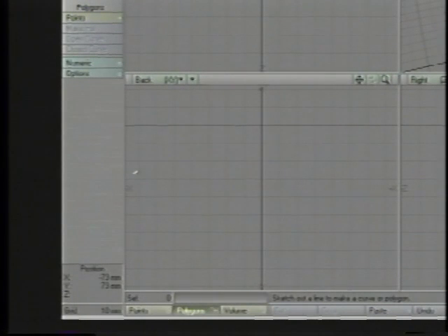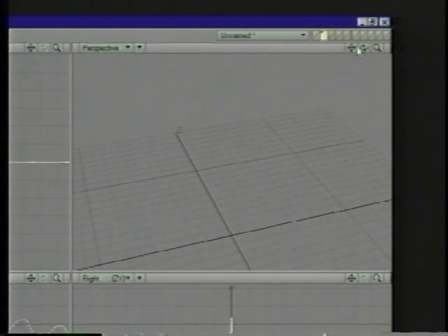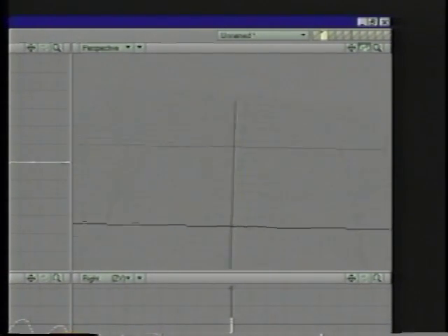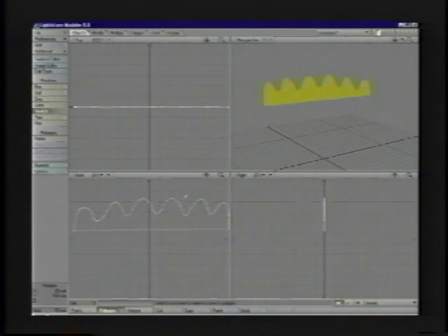Delete this curve and do the same thing, only this time I'm going to create a face instead of a spline curve. Boom, there you go. So that's a polygon like any other polygon. You see that it doesn't show up here in the perspective view. That's because, like we talked about before, it's a one-sided polygon. If I flip around, there it is, and it's there, no problem. So if we want it to be visible, again, we can just hit the F key to flip it around.